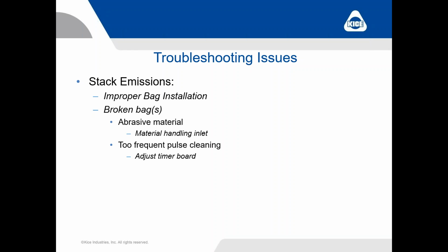Why would you see stack emissions? If you walk out behind the building tomorrow and you see dust and product flying all over the place out of your fan discharge, you've probably got a broken filter bag. Bags will tear over time. Bags will get worn out over time.